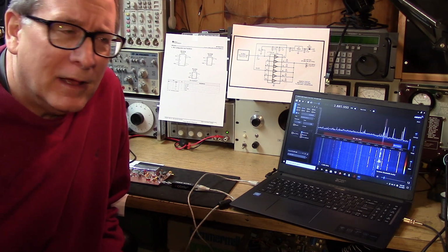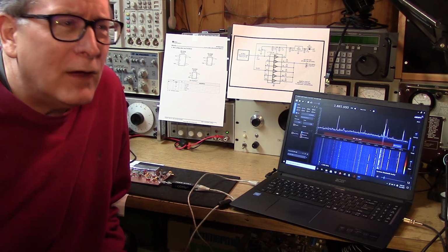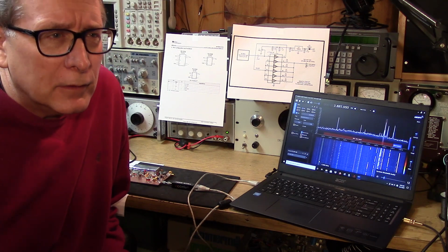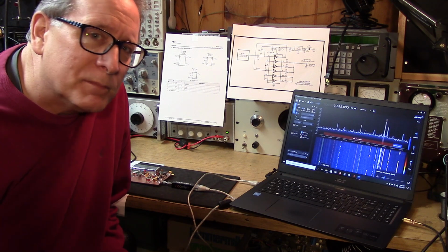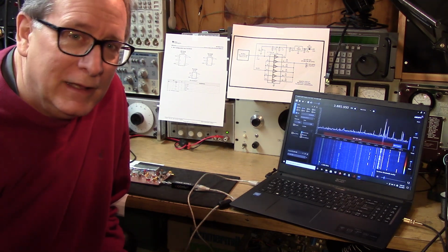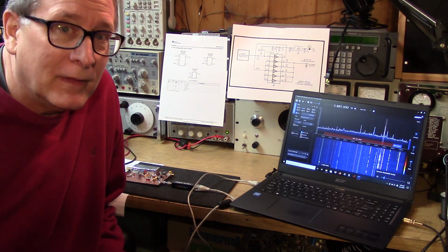They talk about, I have a certain model that fits what the mixer does. It's not really a multiplier. It's kind of a multiplier, but it's got all these other terms too, so don't expect that you're going to get a nice crisp answer like I presented, where it's just a strict multiplier. It's much more complicated than that with these nonlinear systems.